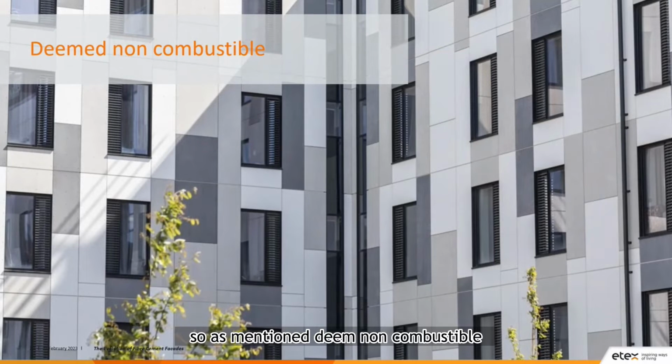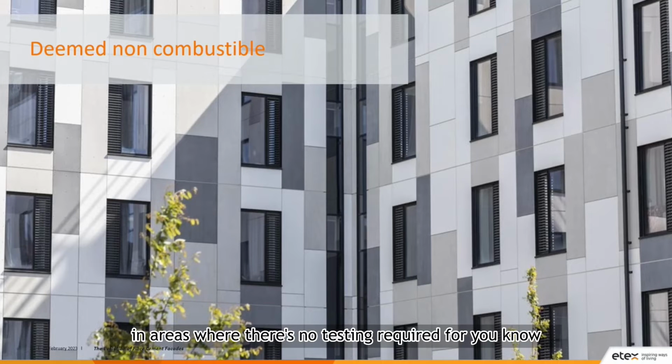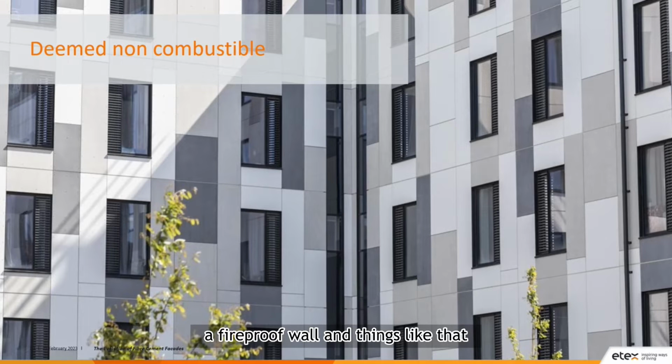So as mentioned, deemed non-combustible. So for the NCC, which is the National Construction Code of Australia, EQUITONE can be used in areas where there's no testing required for a fireproof wall and things like that, because the fiber cement itself, or EQUITONE itself, is deemed non-combustible.